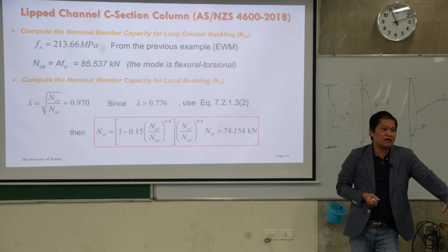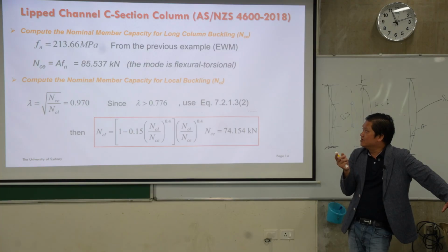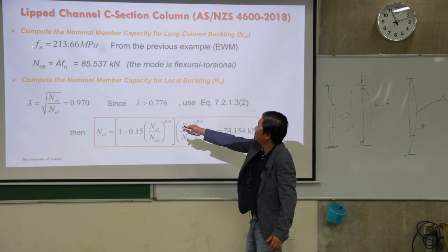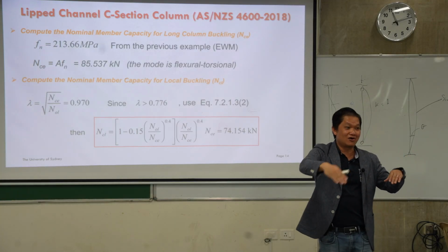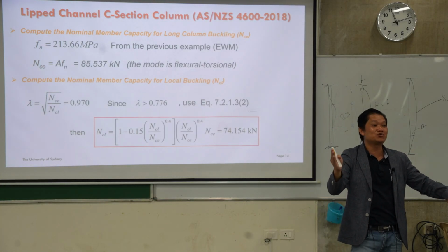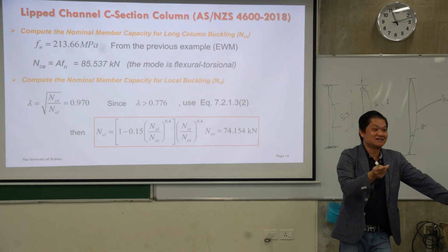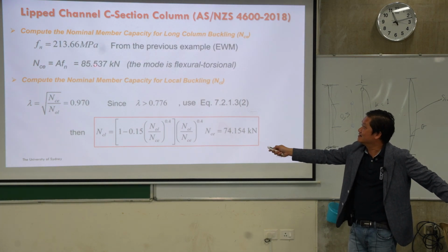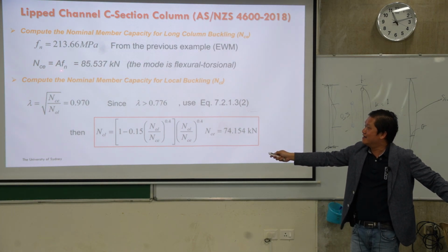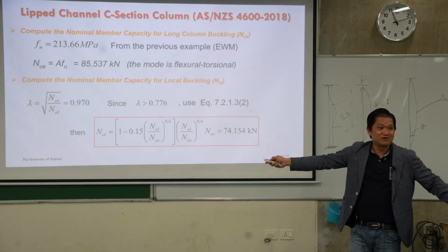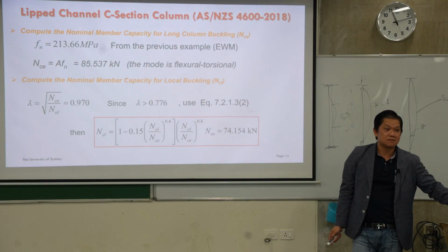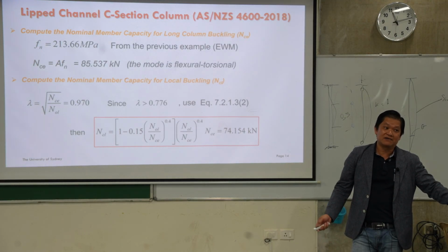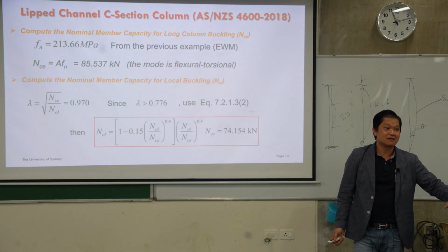No, but then, okay, I get what you mean. You need buckling stress, Fn. It's actually the one that we played with yesterday, right? The buckling stress or Euler curve at the last one. But you need to put it into the strength curve. Instead of doing the effective width calculation, can we directly take that stress and substitute? No, you need to calculate the strength of the flexural torsional buckling. That is there in DSM already.